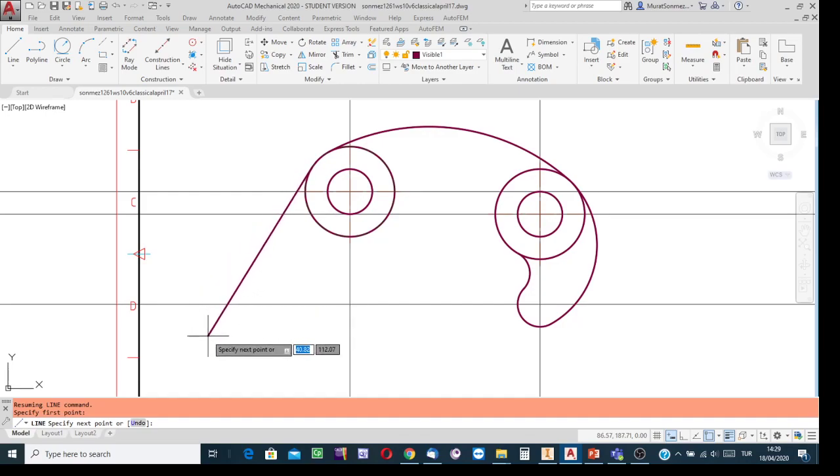Well, the second trick, after saying tangent to the circle, move the cursor in the sense of the line which is to be created. And then, well, here you see along the train the highlighted box ready to gather the length of the line. But the third box, you see there is a number, but we don't know what it is. Well, if it were the case, create a piece of straight line, start the process, then along the train at this stage, we will have a degree symbol within the third box.